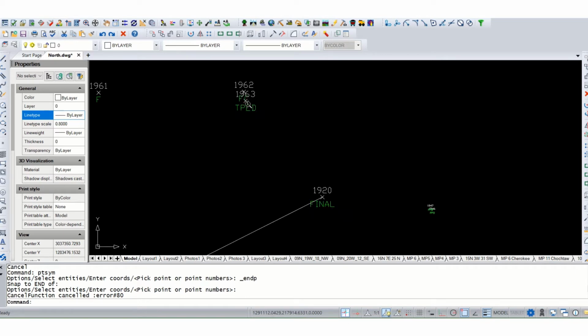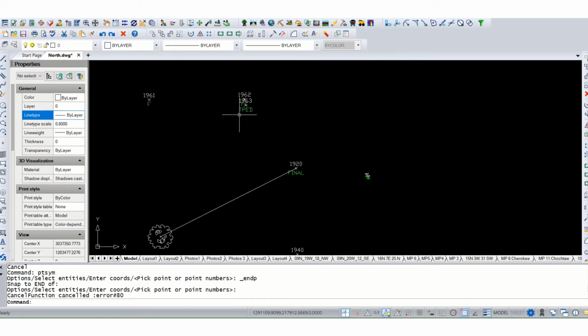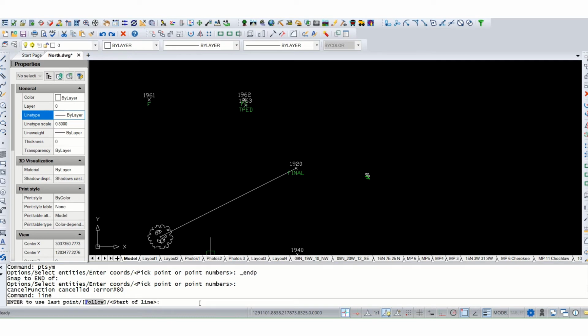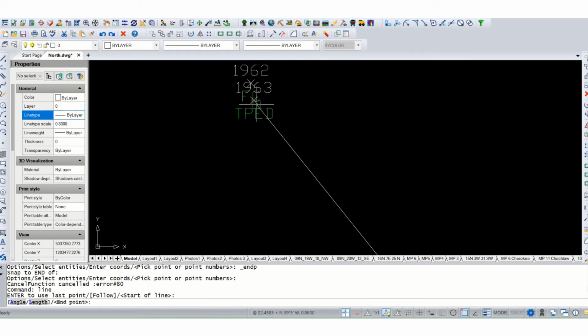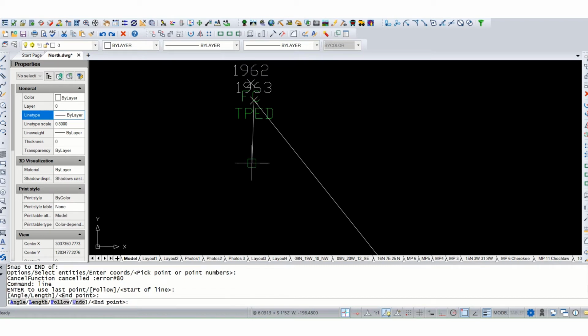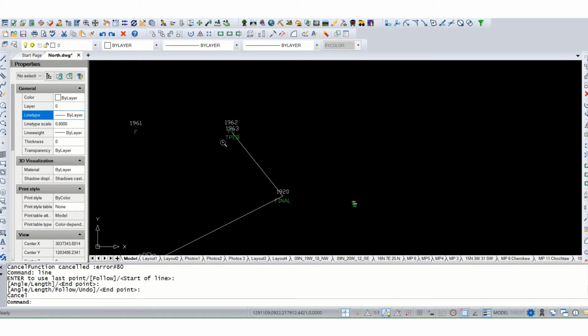Okay, now I've got a fence corner and a telephone pedestal. I wasn't sure which one I wanted to use for a reference, but that telephone pedestal is going to be there for a while, so let's just use that one. I was able to get a direct measurement estimating the center of that pedestal, so I did not have to make any offsets.